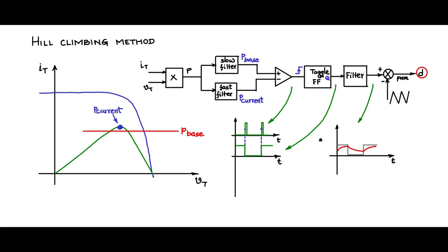So it is moving to the left here, and at this point it has gone down, and there is a toggle, a change in state. When this goes down, the filter output is going down, implying that the duty cycle is decreasing. The moment the duty cycle is decreasing, the operating point is moving to the right. As it starts moving to the right, again it hits at this point. Again you will see that there is a toggle, the filter output increases, the duty cycle is increasing, it toggles again, so it moves to the left.